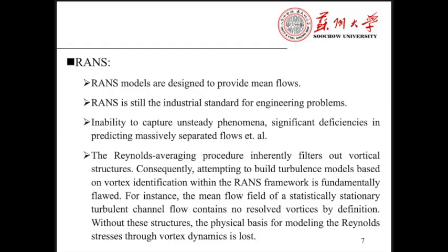However, RANS suffers from its inability to capture unsteady phenomena and significant deficiencies in predicting massively separated flows. The Reynolds average procedure inherently filters out vortical structures, consequently attempting to build turbulence models based on vortex identification methods within the RANS framework is fundamentally flawed.